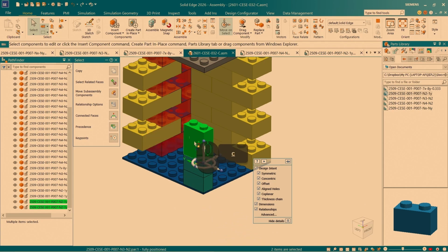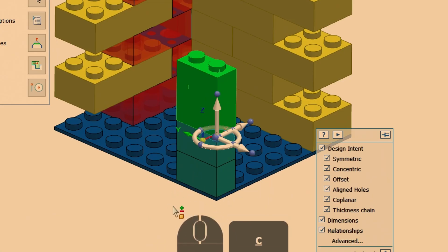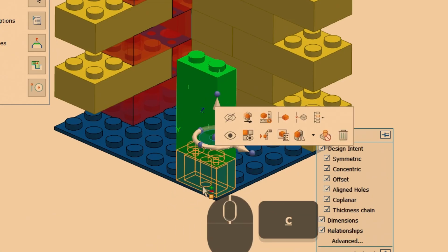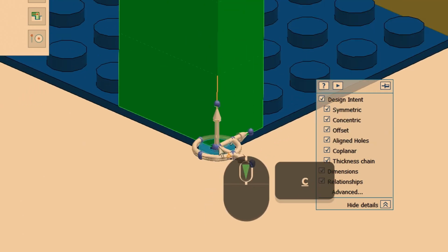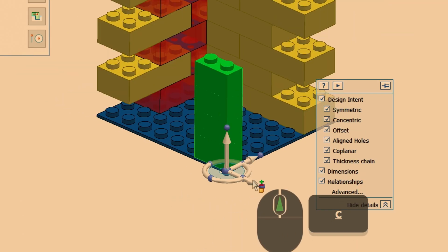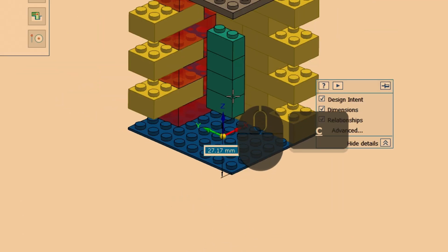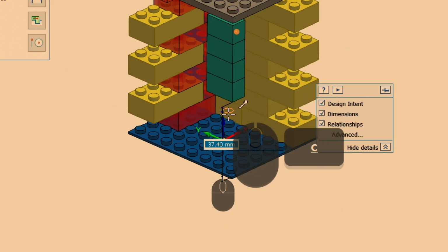And let's try that again. So this time we have the two of them selected, and we have the little plus minus glyph already activated beside our cursor. So I'm going to just choose the two below it as well. And I'm going to move our steering wheel center to this point down here and click. And I'm going to click on this vertical arrow on the steering wheel, try and copy it up to, oh, now you notice they all moved, but nothing was copied.